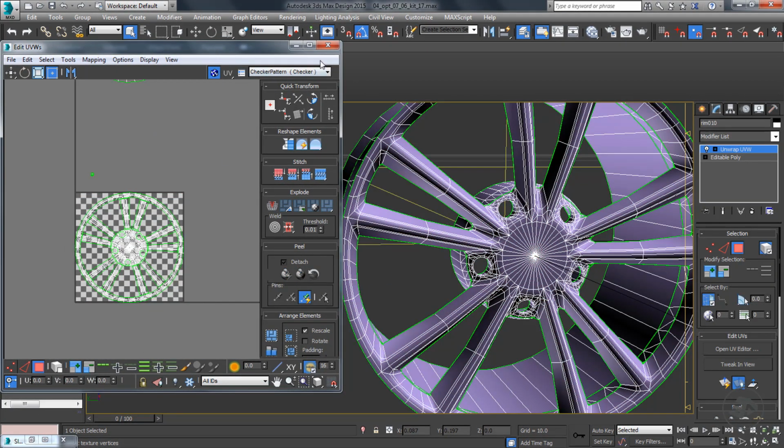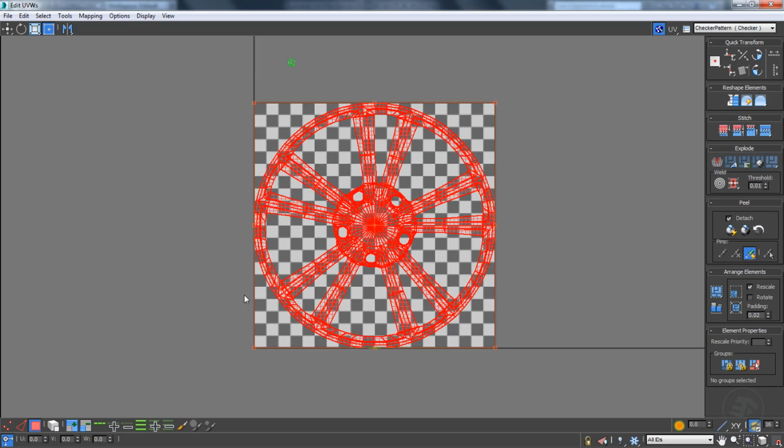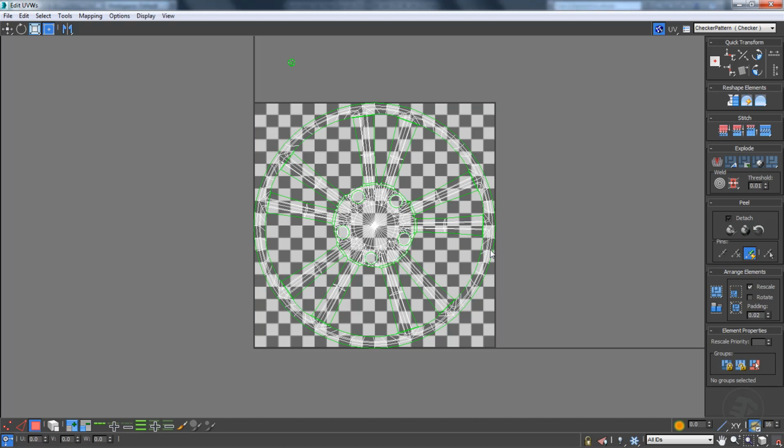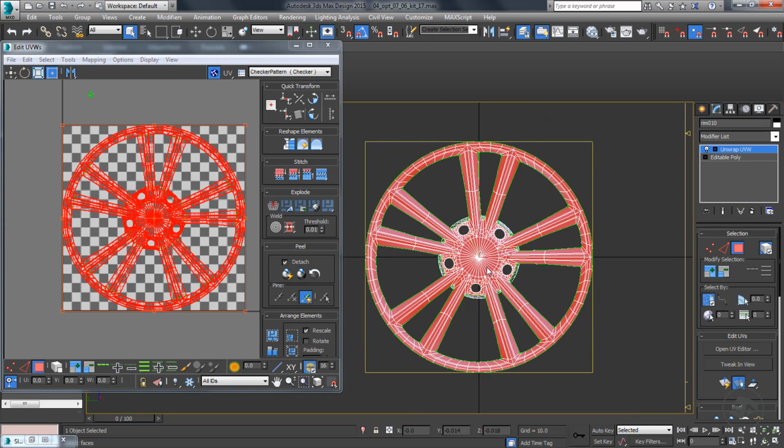The current UV map on your screen will be similar to the one we are going to create for the lower level of detail. However, for the first level of detail, we need the texture to accentuate both the emblem and the pillar's details over the projected texture. We could only project one pillar pair after scaling its UVs over the map, rather than creating a large-scale texture or map to accentuate these repetitive details. Let me show you how to do it.